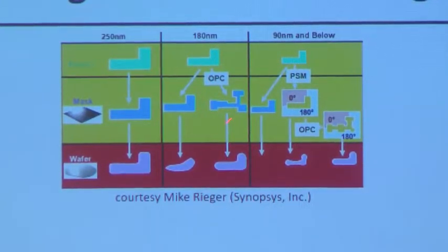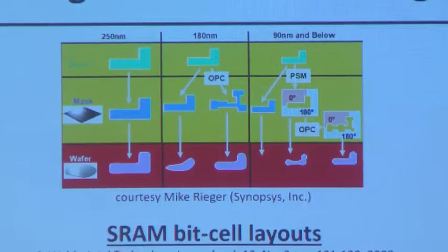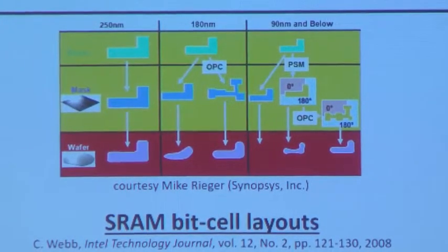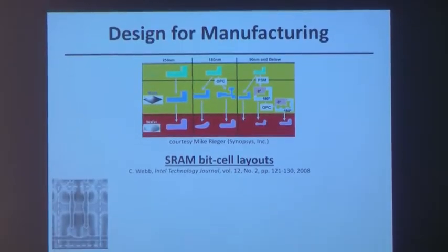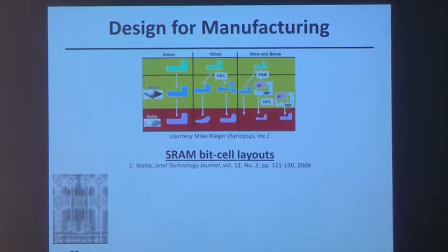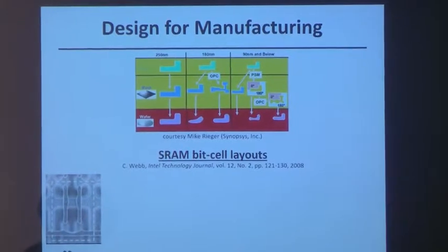So we have things like optical proximity correction, features on the mask, phase shift masks, and changes in the illumination system to try to achieve features on the wafer with good fidelity to what the designer wanted. But bottom line is, as the features got smaller than the wavelength of light, these features started to have curvy shapes, right? So if you want a rectilinear feature, you actually on the wafer did not achieve that. So let's see the impact of this sublithographic patterning issue in real products.